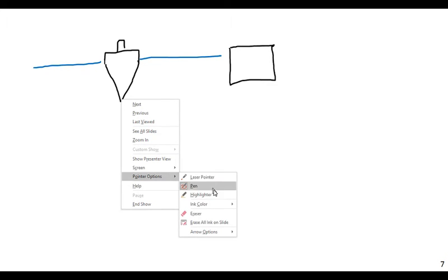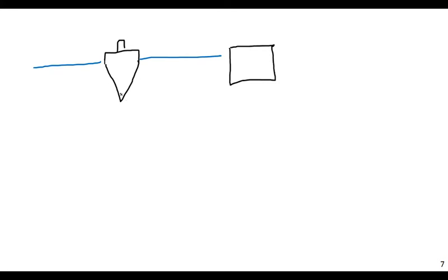But what people usually do to make this stable is to use the idea of ballast, and ballast can be any number of things. The whole idea of ballast is to put a lot of heavy, dense material at the bottom of your vessel. So what can that be? In a simple case, usually you'll have water tanks and things like that. If water tanks aren't enough, you might use steel or concrete or something like that.